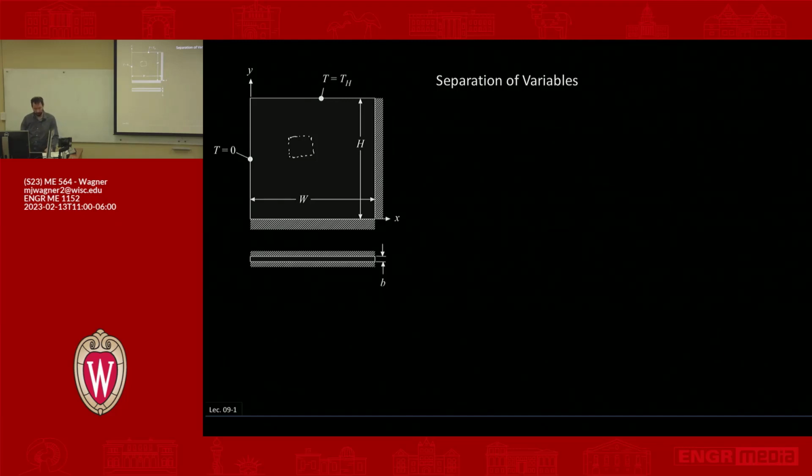What do we have then for heat flows? In x, we're going to have a q dot at x, and in y, we're going to have q dot at y. And we also have heat leaving. So we have heat leaving at q dot x plus dx and q dot y plus dy, where dx and dy are just the height and width. For this problem, let's assume that we don't have generation, it's steady state. So the only thing we're worrying about is heat flow due to conduction.